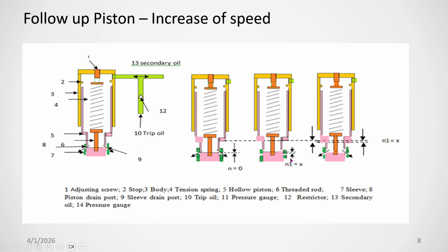We'll close this. You will just close this valve by X1. When you close X1, this oil going inside will pressurize this pilot piston spring and bring it down to show that the steady state condition is achieved. And as the spring is stretched, the oil pressure will increase, and secondary oil pressure is also going to increase. And that will increase this pilot piston pressure, and when the pilot piston pressure is increased, the steam valve will